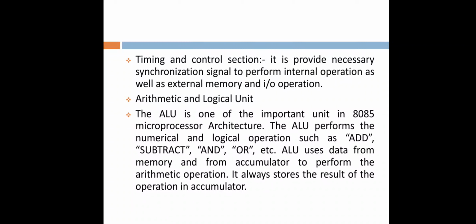Arithmetic and logic unit. The ALU performs arithmetical operations like addition and subtraction, as well as logical operations like AND, OR, NOT. The ALU uses data from memory and from the accumulator to perform the operation. It always stores the result of the operation in the accumulator. So basically the ALU performs arithmetical and logical operations, and whenever the ALU performs an operation, the final result is stored in the accumulator.